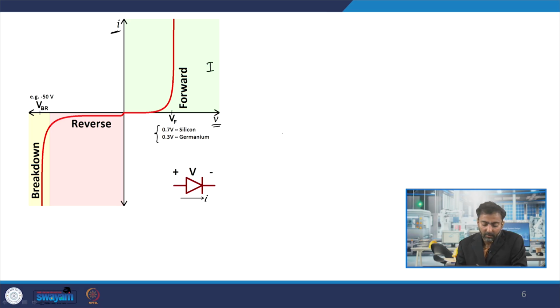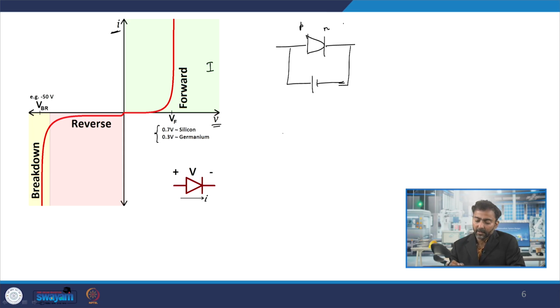And once the threshold voltage is crossed, it is conducting almost linearly; the current just goes up, it becomes like a conductor. So, for a diode, as we understand, we need to forward bias it. Now, what does forward biasing mean? Just to illustrate, for a diode you have a p type and an n type semiconductor, the p-n junction, and you forward bias, or raise the potential of, the p type. Why are we doing that?